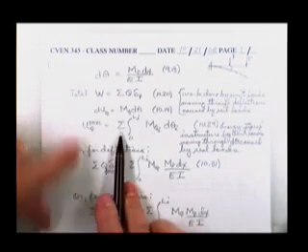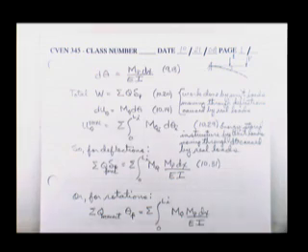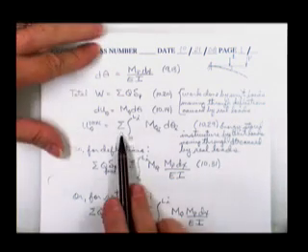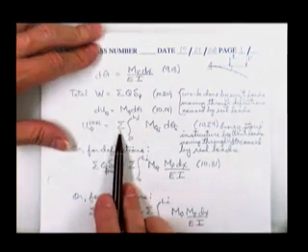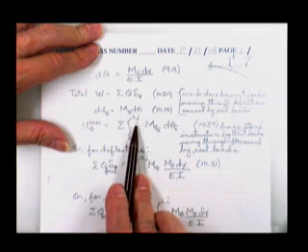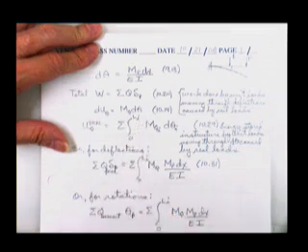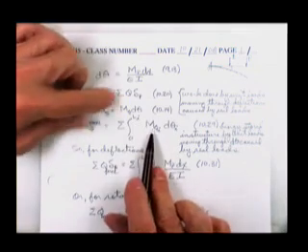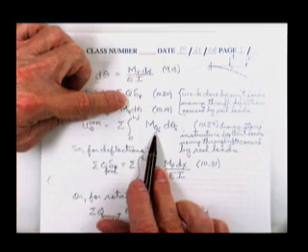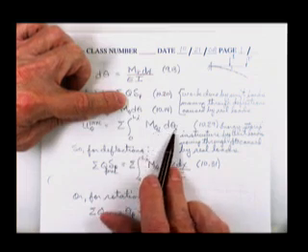And the book doesn't have a sum, but the truth is in most cases you'll have more than one beam involved, so you'll have to sum up all of the individual i equal to 1, 2, 3, 4, 5, however many members you have in the structure, times m sub q due to the q loads times d theta sub i.